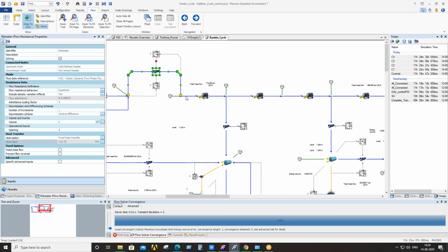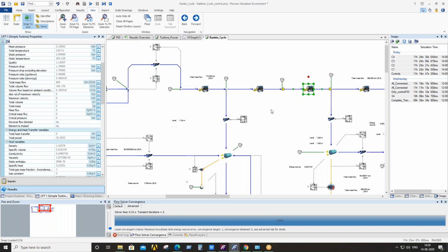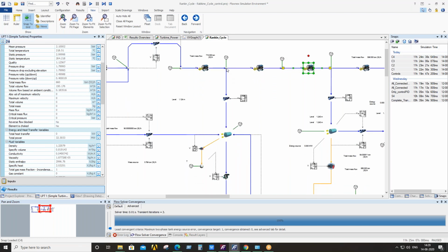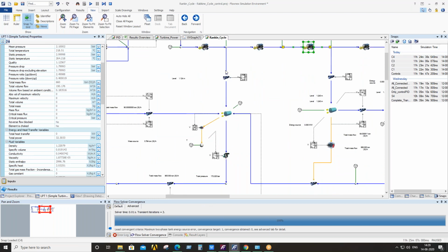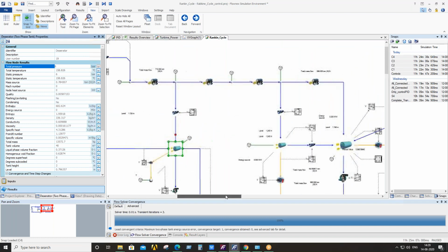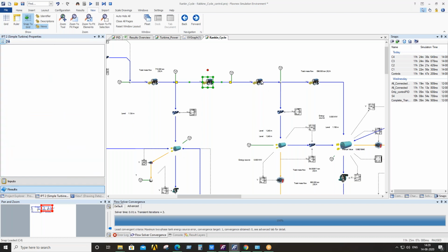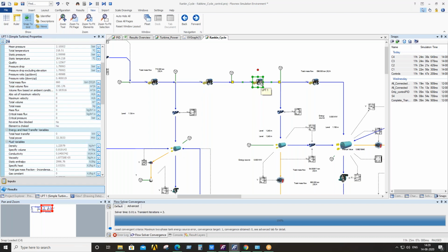And after the reheater, it goes to the intermediate pressure turbines. These three represent the intermediate pressure turbines, and each individual turbine represents the stages for the intermediate turbines. So you can see from the first stage, one extraction is taken out, and this extraction is going to the deaerator, which is maintained at 6 bar pressure. The remaining steam will be expanded through these intermediate pressure turbines and goes to the low pressure turbines.